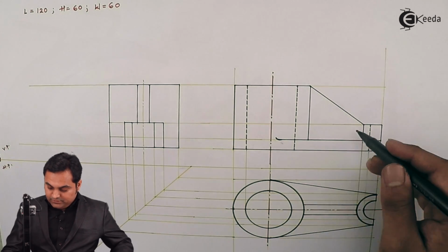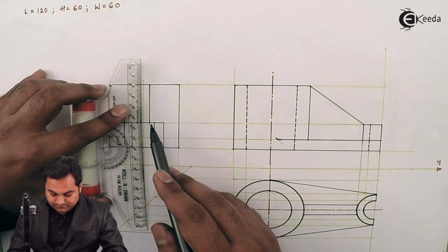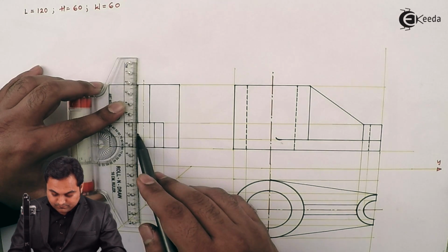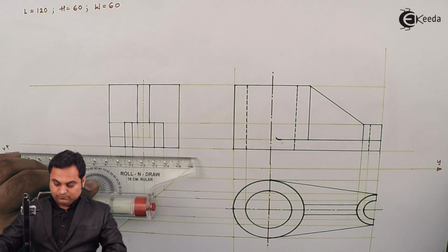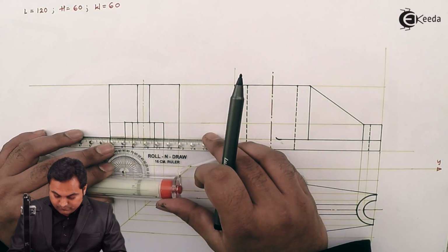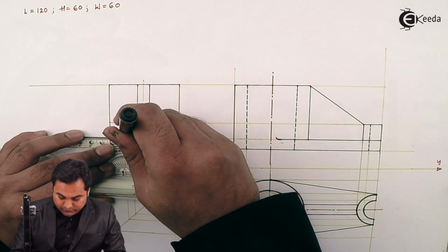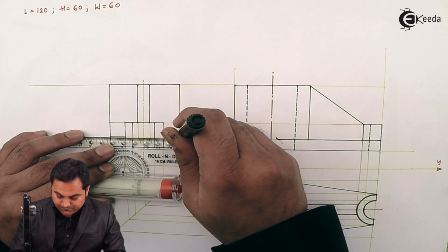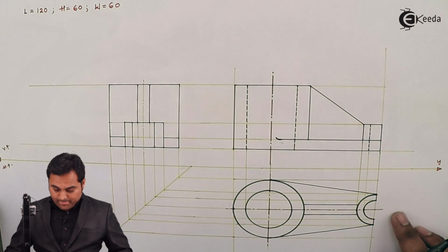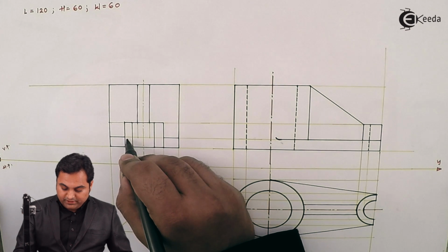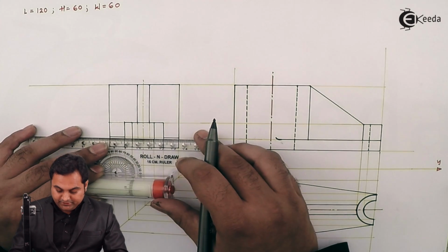And then this rib, I'll extend it up to the bottom. So the dark line up to the semicircle indicates that inclined block of 10 mm height. Then when we extend it, that block will meet the rib, so this much part will be hidden.